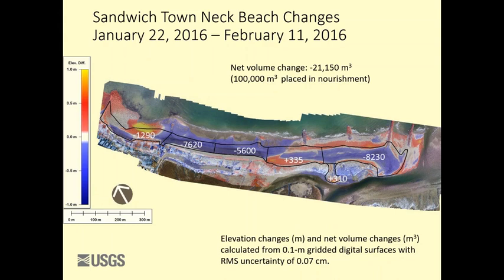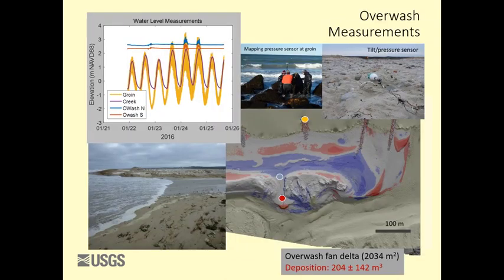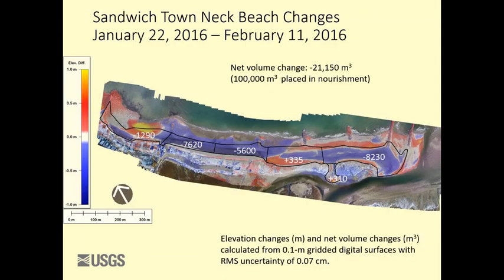up on the beach. The bigger problem is that right about here is where the Cape Cod Canal is, and the source of all the sediment is up here in Plymouth where there are these big bluffs that are eroding. And this is kind of the net drift is along in this direction. And so the sediment supply has been cut off by the jetties for the Cape Cod Canal. And so regionally, over the last 100 years, this area has been starved.